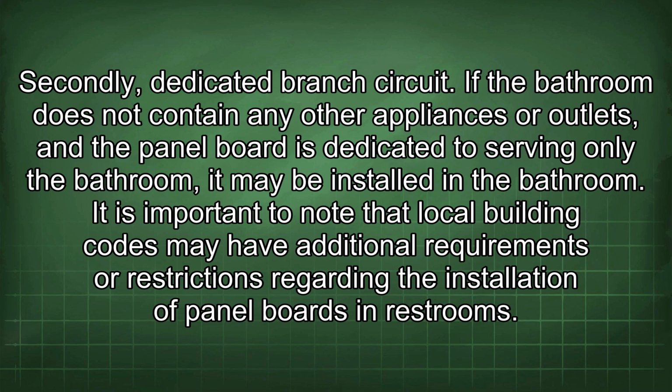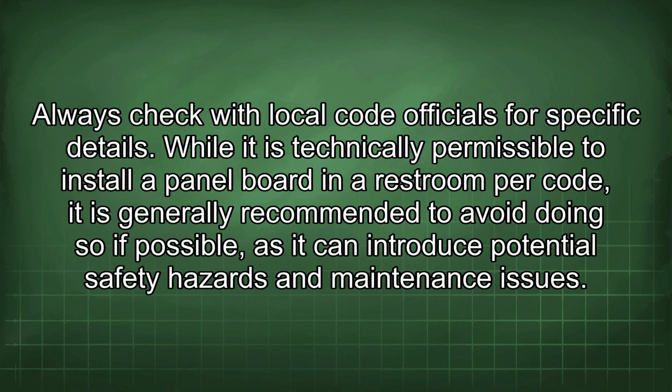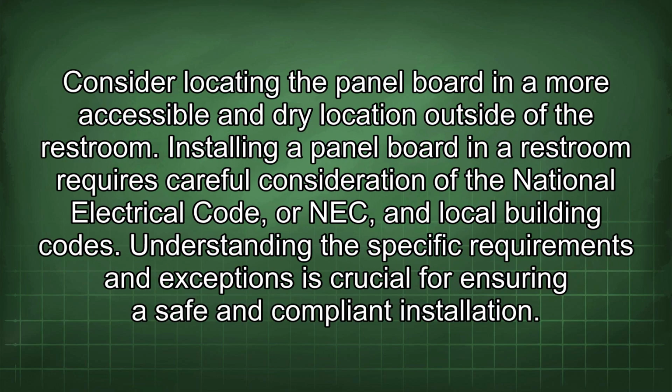It is important to note that local building codes may have additional requirements or restrictions regarding the installation of panel boards in restrooms. Always check with local code officials for specific details. While it is technically permissible to install a panel board in a restroom per code, it is generally recommended to avoid doing so if possible, as it can introduce potential safety hazards and maintenance issues. Consider locating the panel board in a more accessible and dry location outside of the restroom.